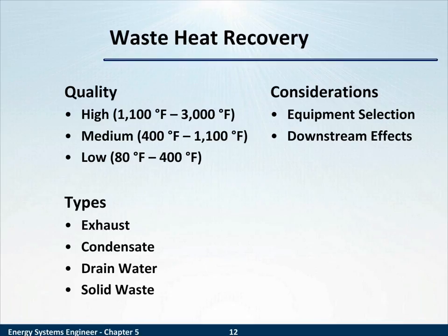Low quality heat recovery can come from processed steam condensate. We saw that earlier. You have condensate from steam that was used for some process, and the temperature of the hot water, the condensate, is somewhere between 80 and 200 degrees. Or processed cooling water.